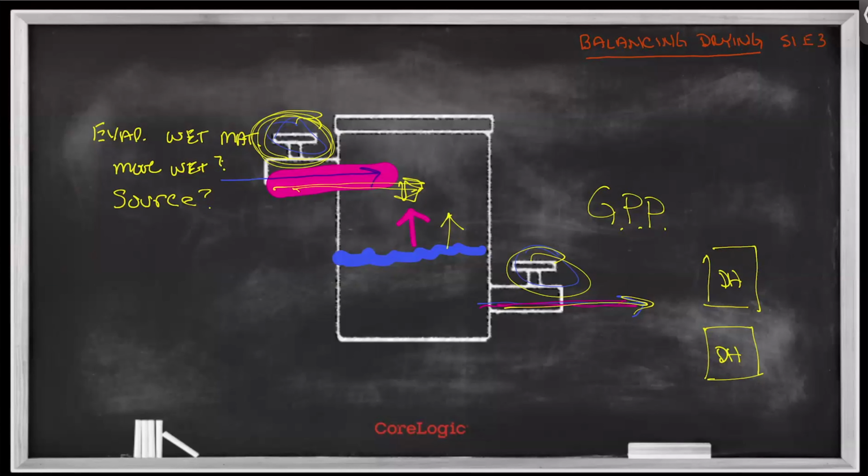Another reason that we could be having this problem is because of infiltration. So infiltration means that we're getting moisture that is entering the structure from somewhere other than inside that space, right? So what is your local weather? What's the humidity like outside? Is the grains per pound outside higher than they are inside? If the humidity outside of the building in terms of grains per pound are higher than they are inside, then you are fighting some level of infiltrating moisture.